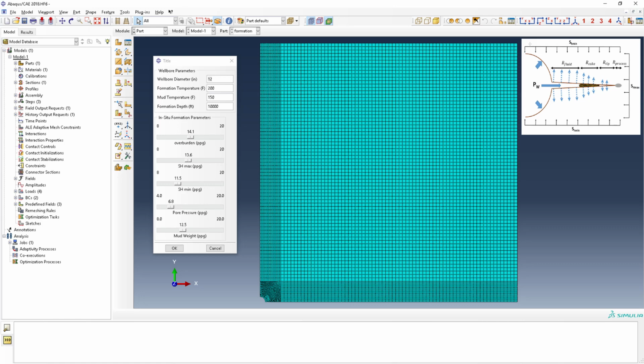This model is used to predict the opening of the crack due to the thermal and mechanical operational conditions of a section of the well, which change depending on the well depth. The model can take any thermal operational conditions as well as anisotropic horizontal stresses and in situ conditions for this portion of the well.